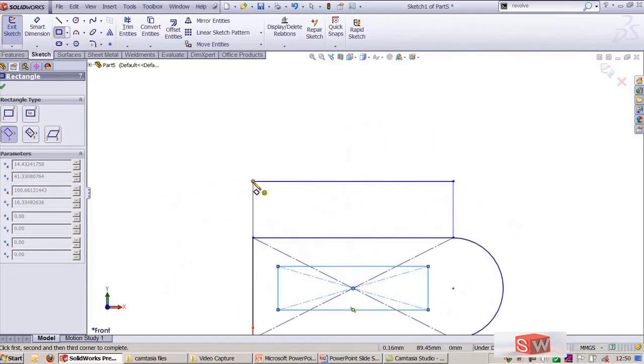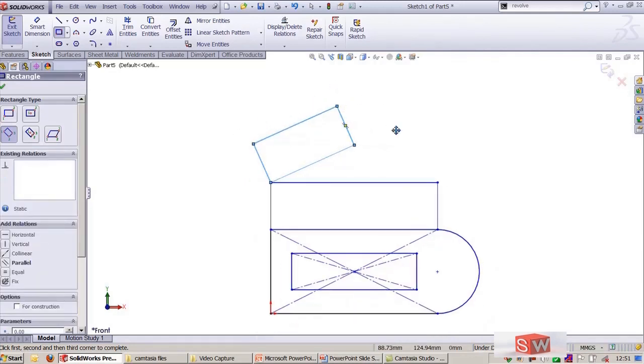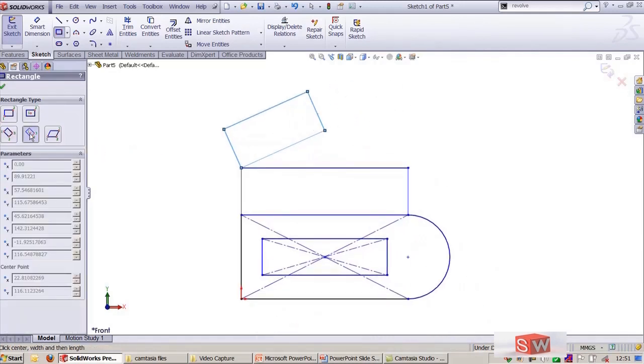You can do this. First point and second point, this is the orientation angle. You can see it gives you distance, the length of this rectangle, and the angle is 25.83. And moreover, it gives you the tracking point where you can see it is exactly matching with the midpoint of the bottom line. Now I will select the second point, and now the direction is moved here, and that distance d equal to 23.98 is showing the width of the rectangle. Now the oriented rectangle is finished.